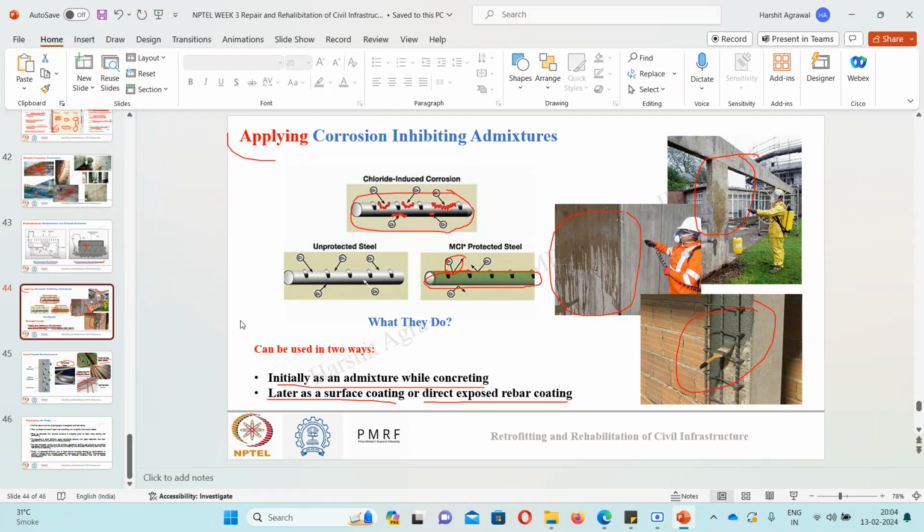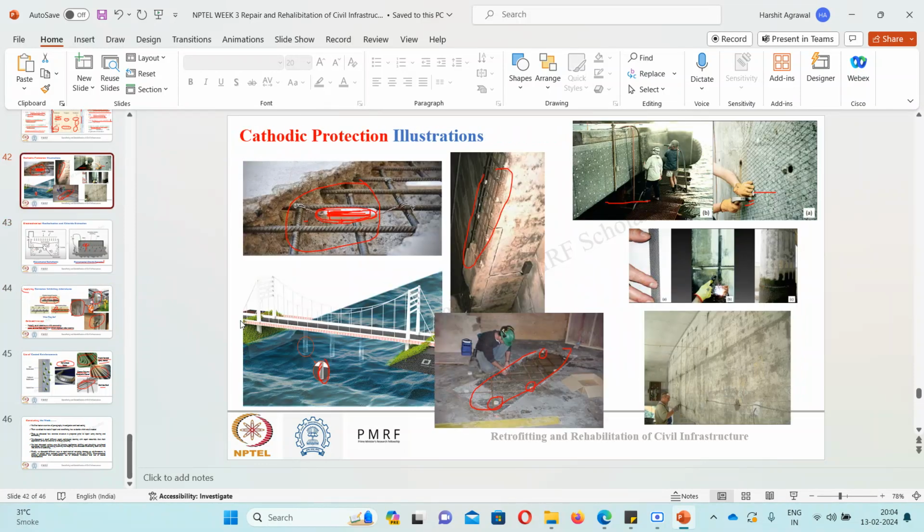And then you can use some coating, which will be a double layer of protection for you. Or if you see it is still not working, then you can go for cathodic protection systems, which you can install on the surface, and you can protect the structure if it is that critical. But corrosion repair is very deep and very complex. So if you have a building or you are managing a bigger project that needs a proper expert solution, then you need to contact proper experts.